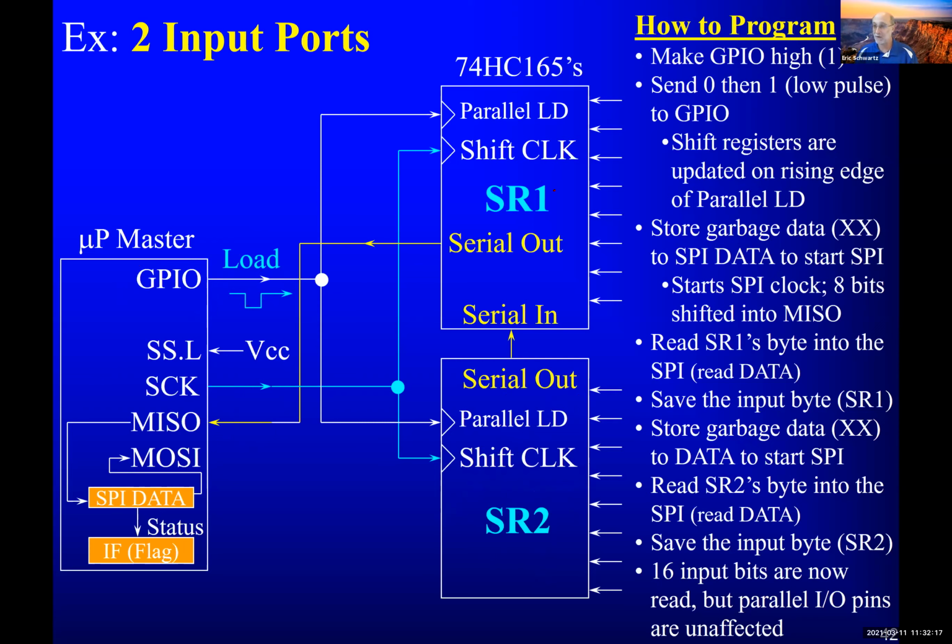We did the internal asynchronous serial communication, and then we had an external chip. We used an external serial port as well, using EBI, the external bus, to control it. And there are external UART chips that have 4 or 8 serial ports built into them. And they're very popular.